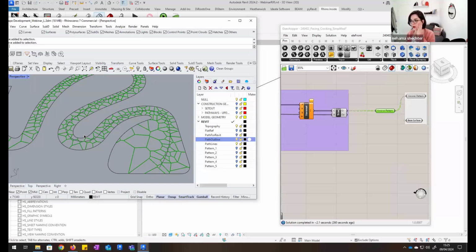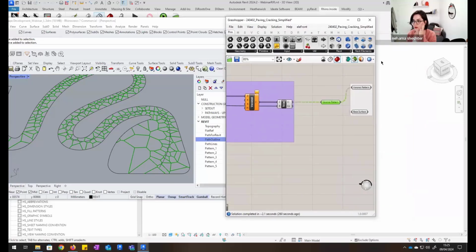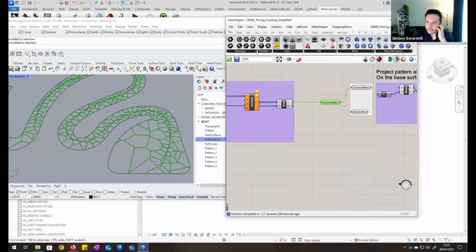These are the top tools that you have there in Grasshopper. They're solely for Revit, right? They're with Rhino Inside. This one, the Revit element, and also those ones will not show up if you open it in the regular environment, just Rhino and Grasshopper. So that's why we split the script. The design script can stay in the Rhino world, let's say, and the Rhino Inside part can go into Revit Rhino Inside, where we have all of the nodes. I'll show you what I mean. It sounds complicated, but it's not.